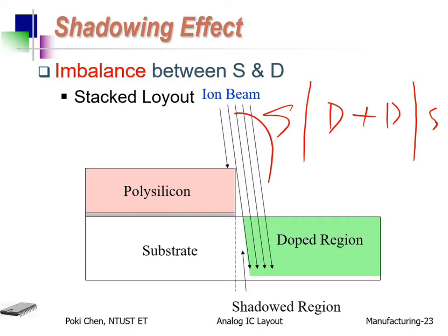So drain and source and drain. This is my own source, you can overlap it. Source, drain, source, you can overlap your drains as you like. That is what we call stacked layout, to deal with such a tilted wafer implant. It must be done, more exactly for your critical devices. Alright?